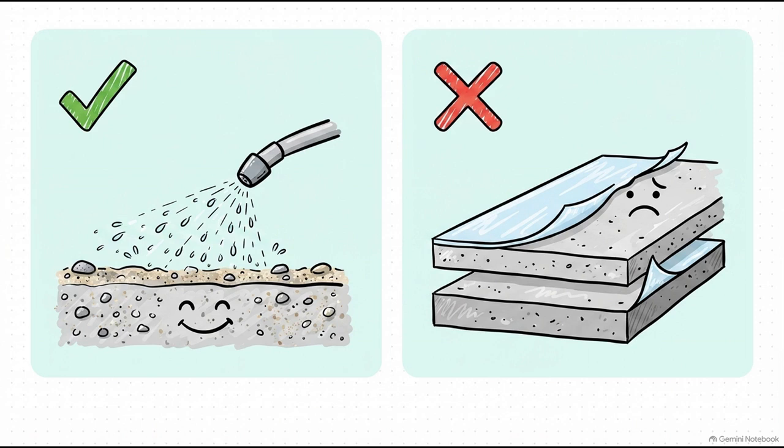Using a curing compound that acts as a bond breaker is literally like trying to put duct tape on a greasy floor. The next layer just won't stick. You have to verify that the curing method is compatible with future layers and strictly follows the project documents. Bottom line, never assume a final finish curing method is suitable for an intermediate bond surface.